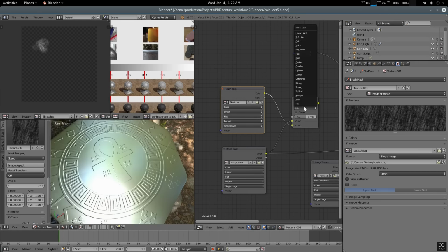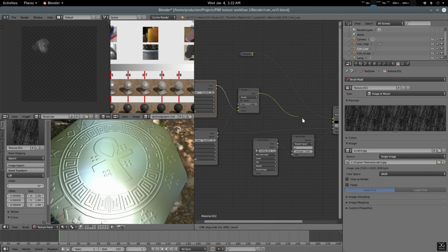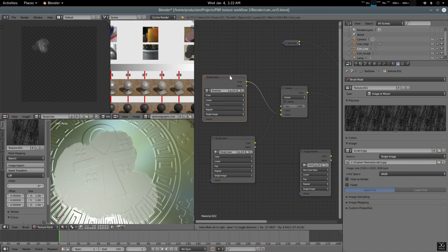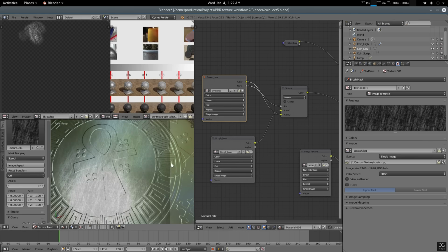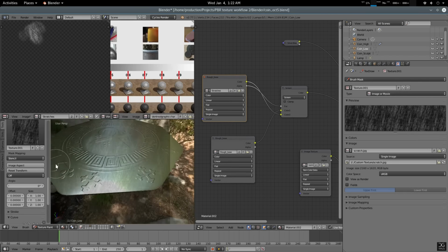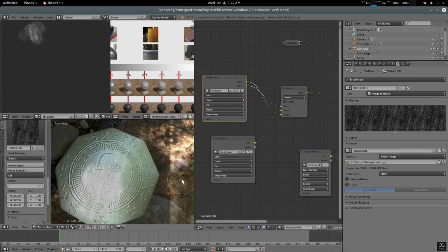We cannot see it because we haven't joined them together. Let's go to the screen, use factor 1, and let's join them together again in the roughness panel. Alright, now we're seeing something, and the rough base should have an alpha factor here. There we go. Okay, so it is deriving the alphas from the rough base and taking the factors here. So now we're seeing our scratches. So yeah, that is the philosophy.